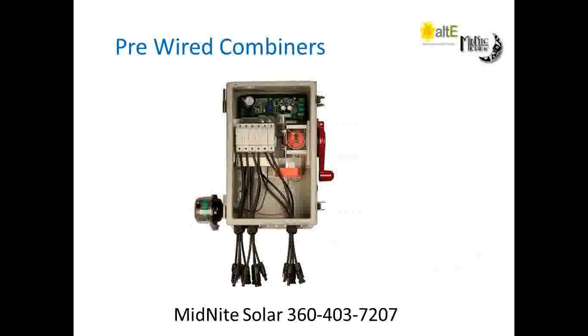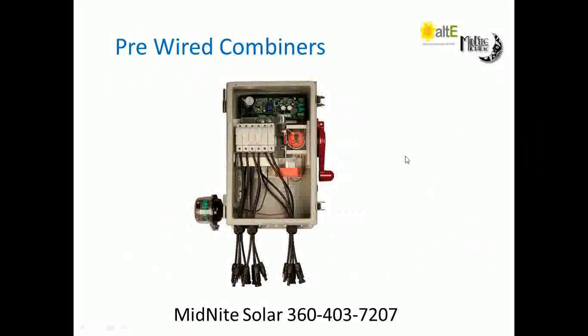But basically what the NEC is going to require is that the whole system be brought to safe operational voltages of, I believe, less than 40 volts, but don't quote me on that. And they're giving you so many meters from the solar panels and so many meters from the batteries. So basically what they're saying is the combiner box and all battery-based breakers need to be turned off with a single push of a button within X many seconds, and I believe it's a couple seconds. It may be 10 seconds. Again, don't quote me on that.